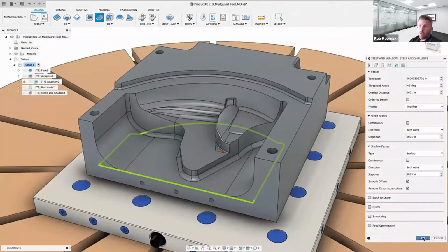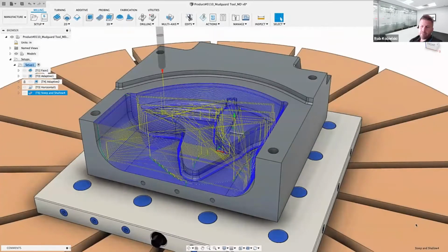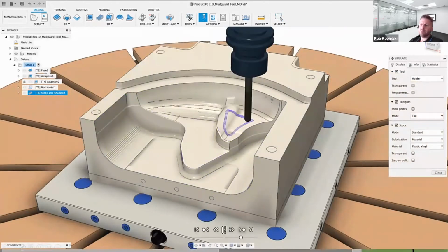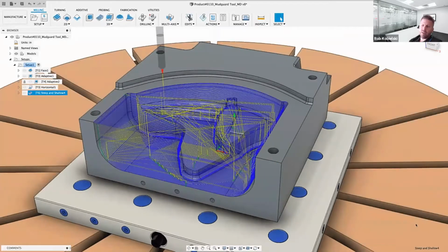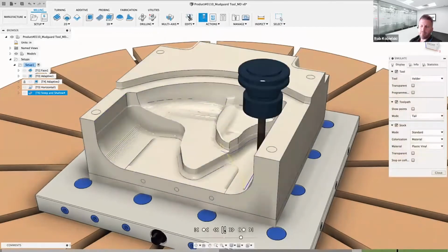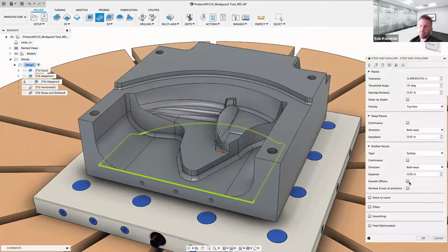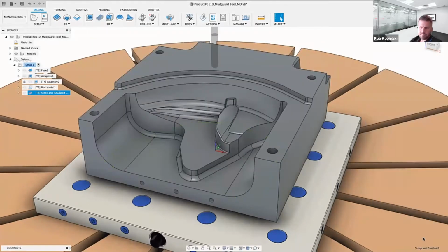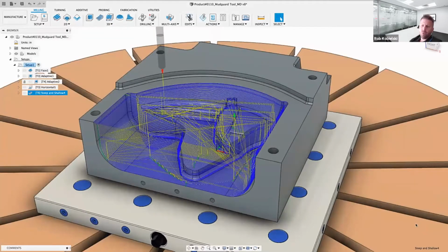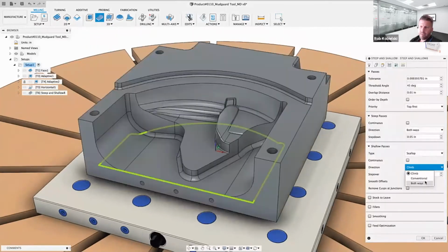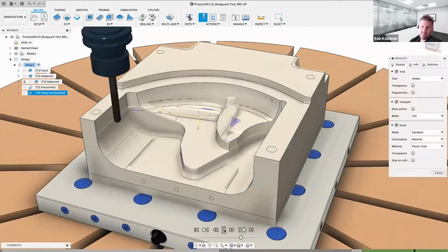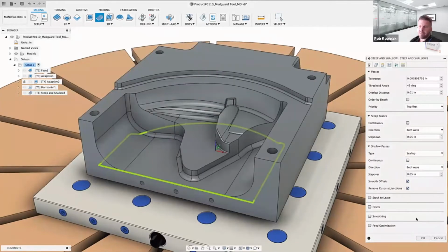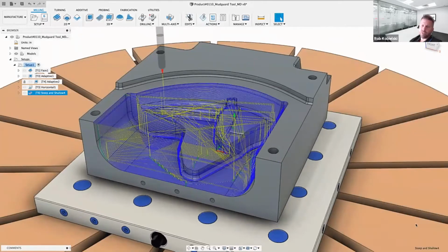For finish machining, the programming of feature-rich freeform parts can be a time-consuming activity by experimenting with different toolpaths to get the right result. The single steep and shallow strategy combines the strengths of varying 3D finishing toolpaths by automatically detecting surface slopes and applying the appropriate strategy for each region. What's more, there's a wealth of options to control the output, all from a single location. These controls include the ability to choose your finishing style for the shallow regions, enable continuous passes, set the cut direction, step over, and of course the overlap distance, which smooths that transition between the regions.